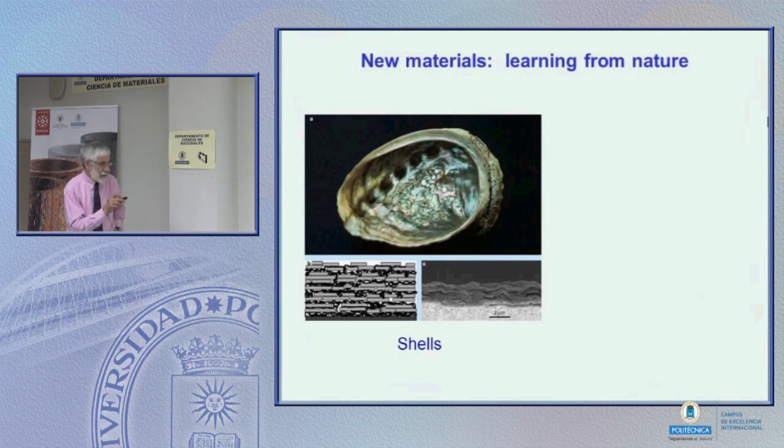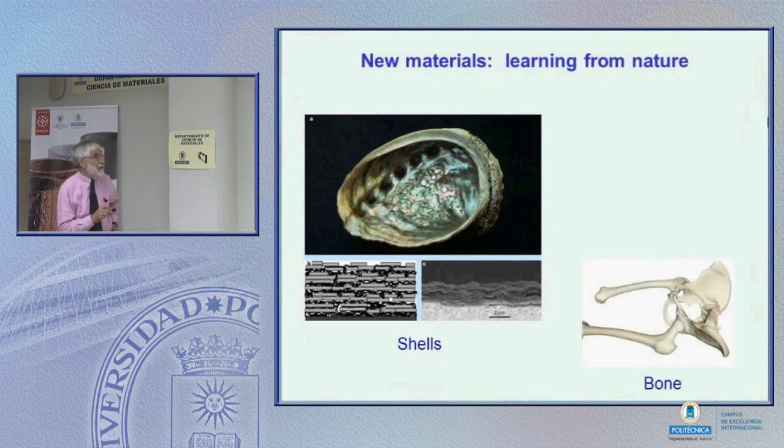Now, the important thing, well, the modern composite, although people say, let us put our fibers into our matrix, it's actually very important not to have the fibers perfectly bonded, really, really strongly bonded to the matrix, because sometimes you want to design it so that when it is breaking, then the fiber will pull out of the matrix, and in pulling out, it absorbs a lot of energy. So it is both strength and toughness, the absorbing of energy. And this is what the seashells are good at.